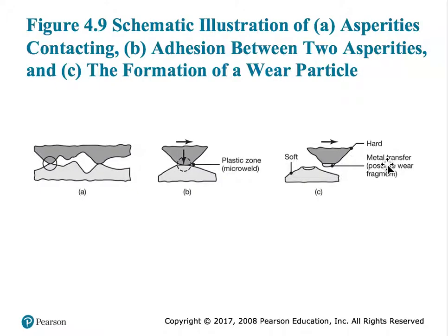And then what you might even find is that, especially if it is a material like aluminum, aluminum can score very easily compared to, say, steel or carbide type of tooling tips. So the tooling tip can get smeared with the softer material like aluminum, which will actually reduce the effectiveness of your machining process, or your final part fabrication process.